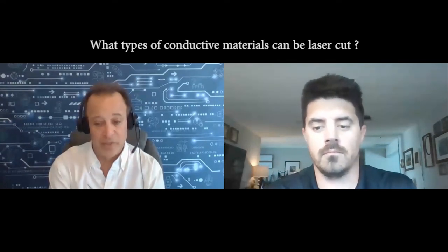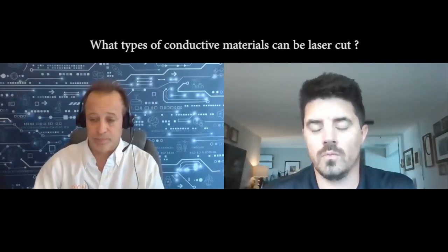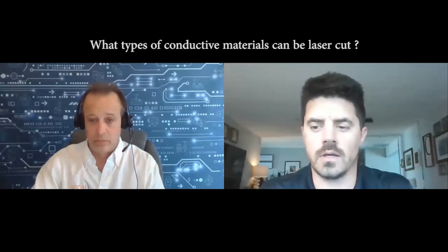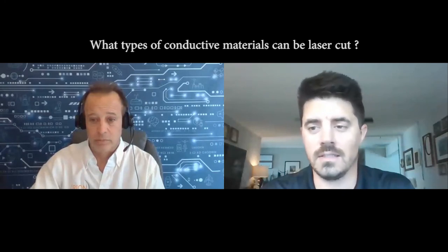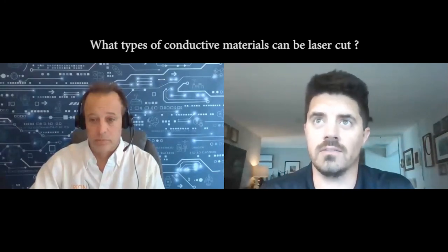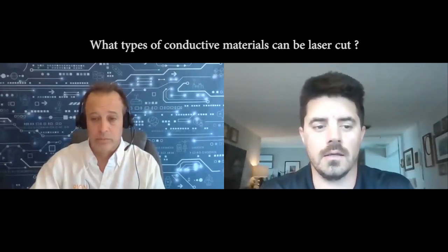Next question. What types of materials can be laser cut? This is a follow-up to the last question. We can laser cut most of our materials: pre-tin plated steel, alloy 770, all of our conductive elastomers, the conductive foam, fabric shielding gaskets (FSG), and oriented wire as well.